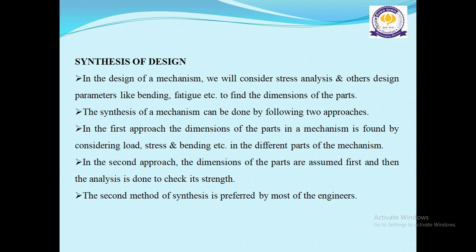In the first approach, the dimensions of the parts in a mechanism are found by considering load, stress and bending, etc. in the different parts of the mechanism. In the second approach, the dimensions of the parts are assumed first and then the analysis is done to check its strength. The second method of synthesis is preferred by most engineers.